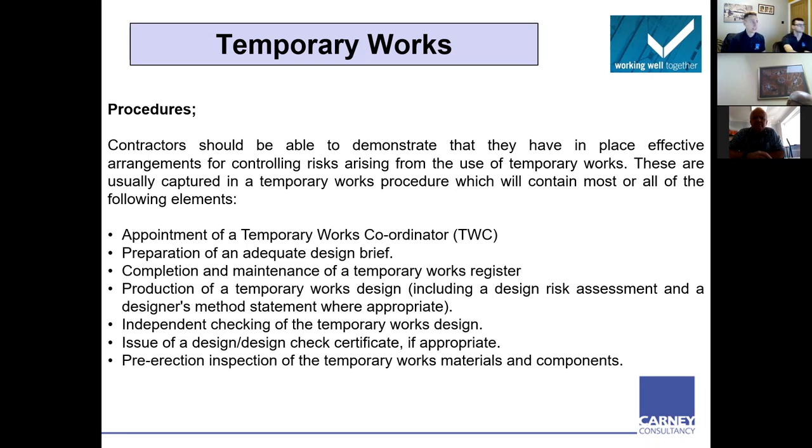So the first thing there, appointment of a temporary works coordinator. Now, some of you may have temporary works coordinator training, absolutely perfect. And you'll know that a temporary works coordinator's job is not to do temporary works, not to design temporary works. You are just a trigger. You're a trigger to say, yes, that needs a design, or, I'm not too sure on that, I think that could do with a design. You're not actually carrying out the work. You're a trigger to ensure temporary works are carried out properly, suitable and sufficient.